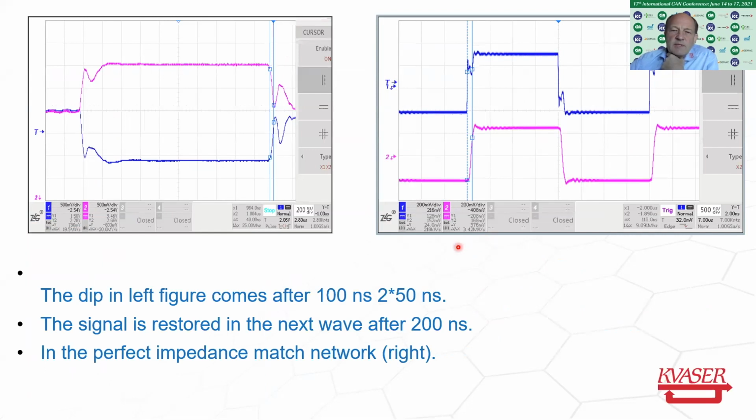What we have seen so far is the S12 measurement, where we have a perfect matching at both ends. So it's an impedance matched source and an impedance matched receiver. So it's a perfect installation, and that's not true, because if you look at the CAN bus, the CAN driver doesn't have an impedance matched output, and the termination is not located exactly where the CAN drivers are installed.